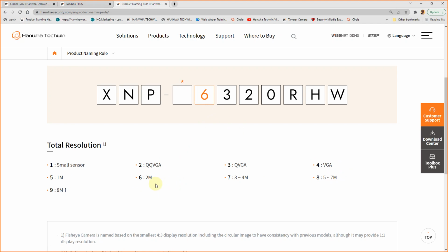What you have to take away here is if your project as per regulation requires 5 megapixel and by accident someone quoted number 6, it should give you a hint something is wrong in the project. Every camera should have the same number in your project, because when a consultant is designing a project, he will not design some cameras 2 mega, some 5 megapixel. Depending on the resolution, the distance of coverage will change.